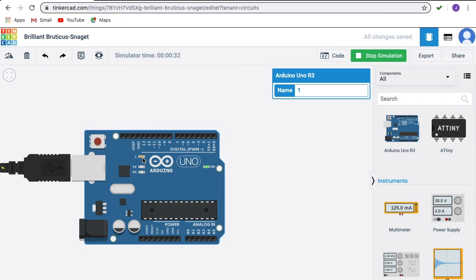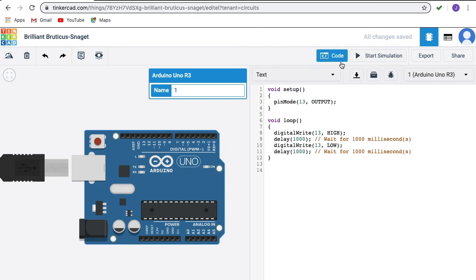So your objective is to change the duty cycle. If you consider this as a square wave, it has a 50% duty cycle. So if I want to change the duty cycle to 75% or 25%, how will you change? Yes, exactly, you have to change the code. If I want to change the duty cycle, I have to change the delay time in the program.